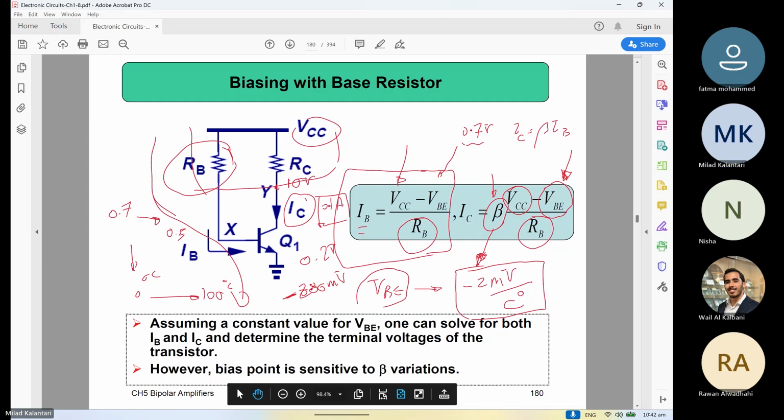One, right? Basically, the power of each component is V times I, right? Voltage is 10 volt, and the current is 0.1 amp, so basically it is 1 watt. 1 watt is dissipated inside the device.